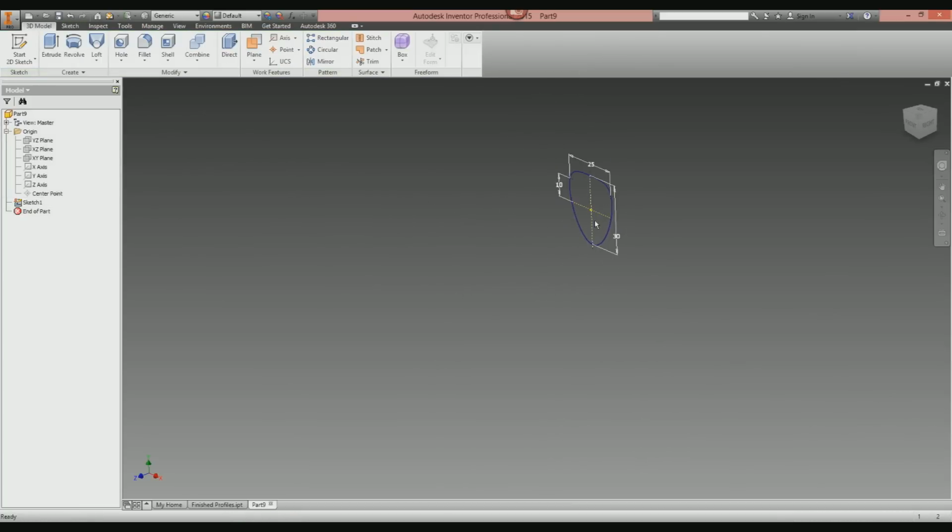Now the next thing I want to do is create a path. Now the path is going to kind of be like a center line that the loft's going to go through. You can loft between 2 profiles. I could just draw another egg-shaped profile here and just loft in a straight line between 2 points. But you can also loft and tell it to follow a curvy path if you want. What do I mean by that?